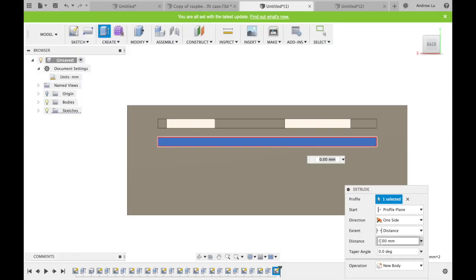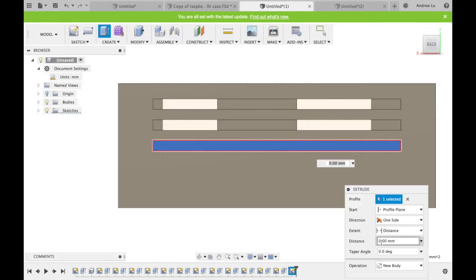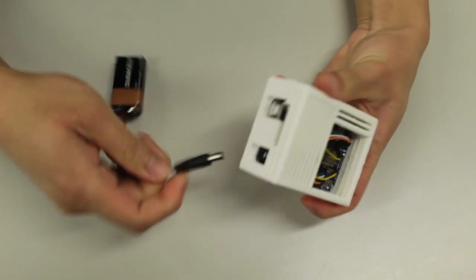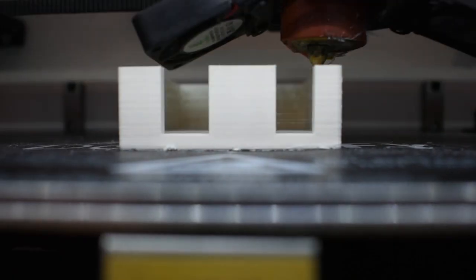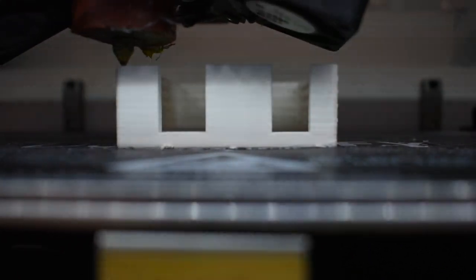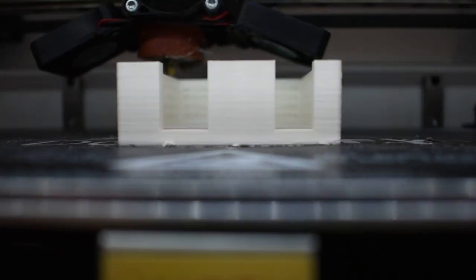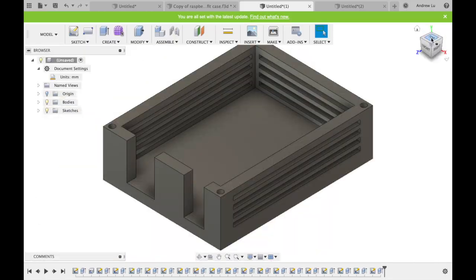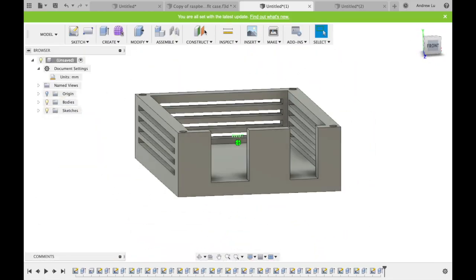The case still provides adequate ventilation through these inhibited slits, but the primary ventilation depends on the slits and opening on the top piece. Another issue included slight errors in measurement that resulted in the ports not being aligned with the openings in the case, but they are still accessible. Similarly, errors in measurements resulted in the height of the case being greater than that of the sensor, resulting in the SD card being inaccessible, but this was easily corrected by elevating the sensor and placing a folded sheet